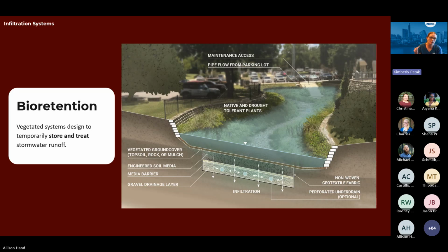If you want to just do it sod lined to be able to reduce maintenance, you can go for that, or it can be a beautiful amenity and a pollinator habitat for a community if you were to do densely rooted plants and also add a tree canopy and such. But depending on your infiltration conditions, if you end up having to do an underdrain with the facility and you also want to install trees or bigger rooted species, you really need to think about the tree root zone and make sure that it does not impact the underdrain system.